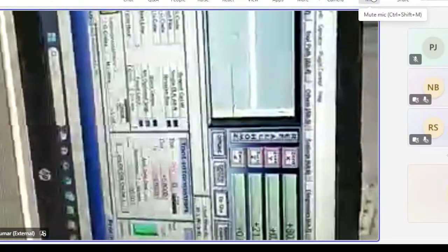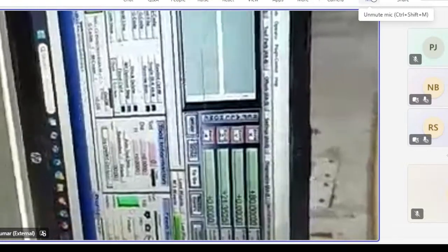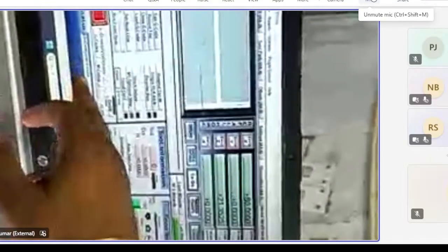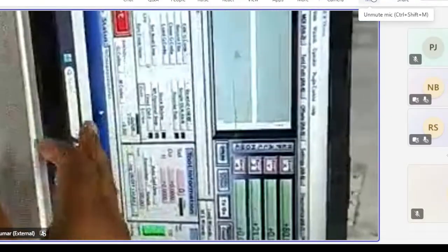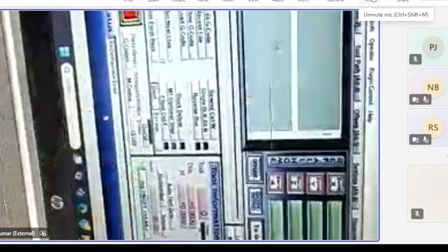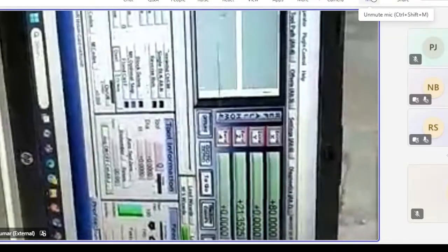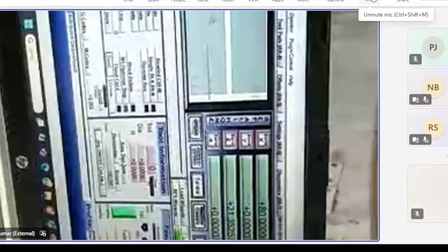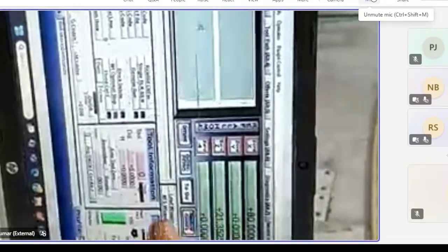So this is the interface of the Mach 3 software that we see. Initially, after starting it, it is showing some configuration, that means reconfiguration e-stop, that is showing the emergency stop. For that, after opening this software, we have to go for the reset. Then it is showing that RNC motion is not found. That means we have started the software, but we have not connected the controller part to this software.